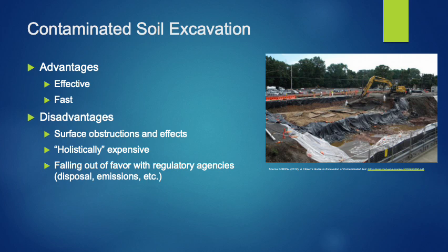But from a disadvantage standpoint, it's holistically expensive. It does create material that needs to be off-hauled and taken to some type of appropriate disposal facility, which creates traffic and emissions related to trucks, as well as wear and tear on roadways. Also, if there are improvements present at the site, such as parking lots, structures, utilities, or other infrastructure, this can pose a risk or prevent digging from taking place. It also has fallen out of favor recently with regulators just because of all of these issues. You are creating something that still needs to be disposed of, you create emissions, and from a sustainability standpoint, it's just not quite favorable.